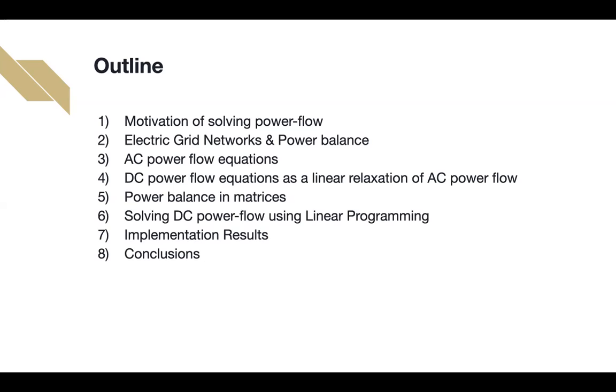And then the next thing we're going to be looking at doing is taking a linear relaxation of those AC power flow equations. And then we call those the DC power flow equations, which despite the name have nothing to do with DC current, unlike the AC power flow equations, which are derived from the nature of the AC current.